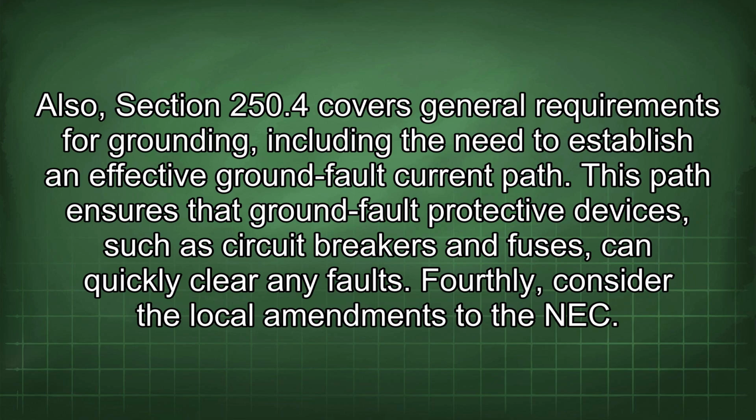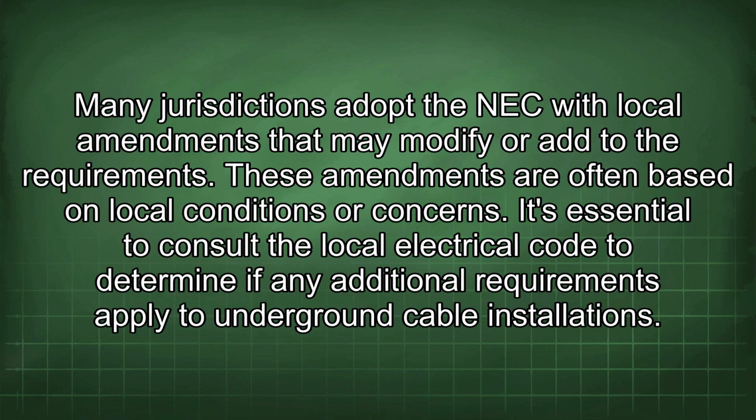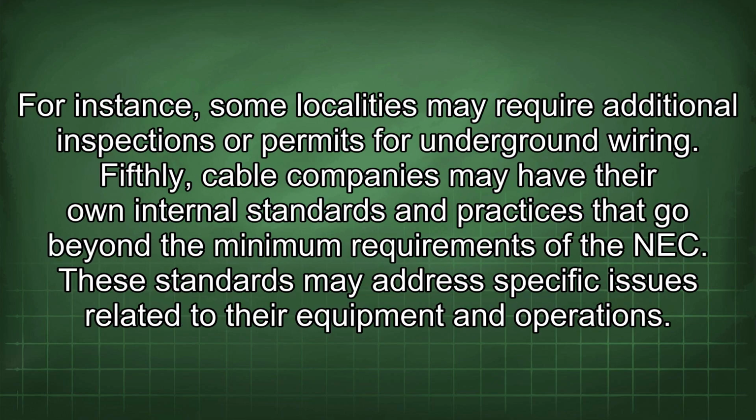Fourthly, consider the local amendments to the NEC. Many jurisdictions adopt the NEC with local amendments that may modify or add to the requirements. These amendments are often based on local conditions or concerns. It's essential to consult the local electrical code to determine if any additional requirements apply to underground cable installations. For instance, some localities may require additional inspections or permits for underground wiring.